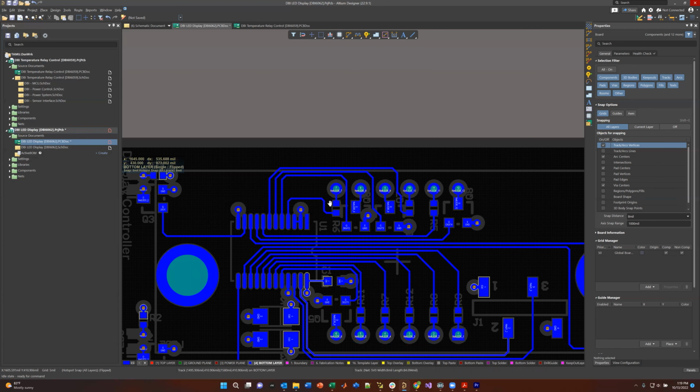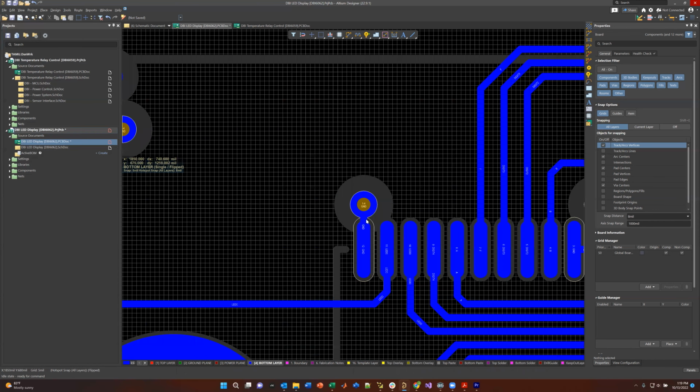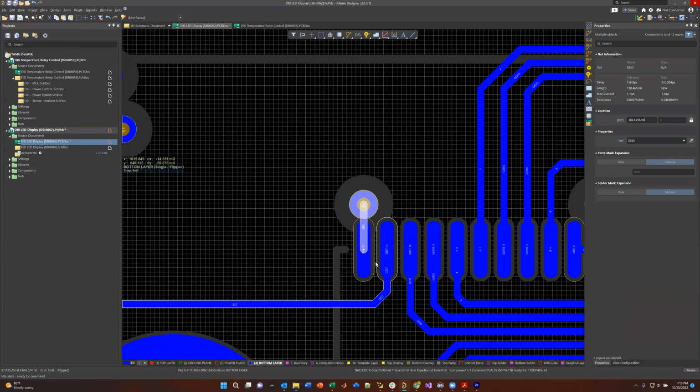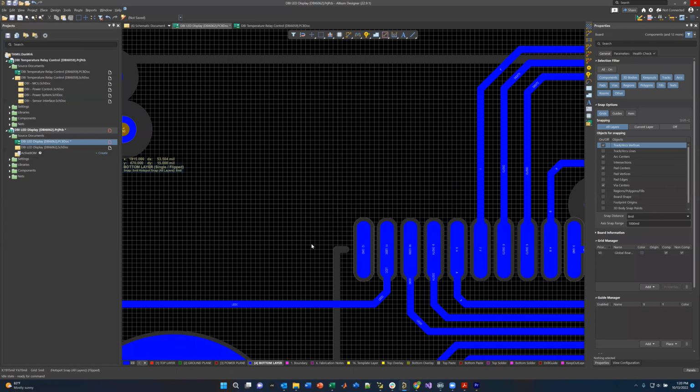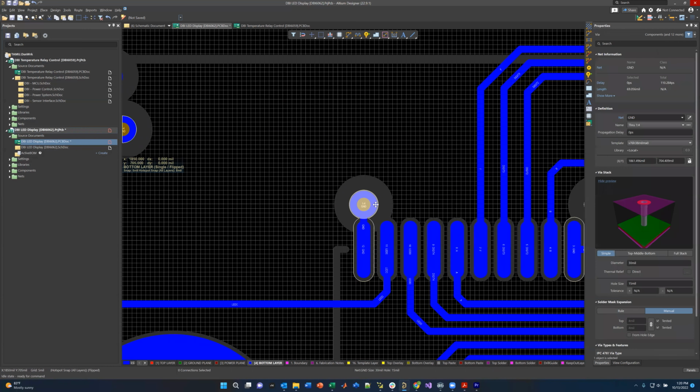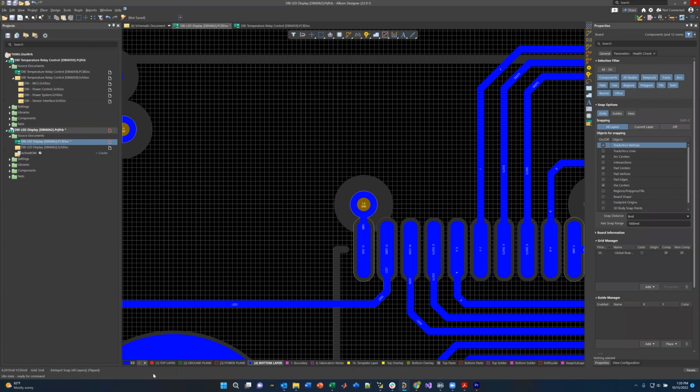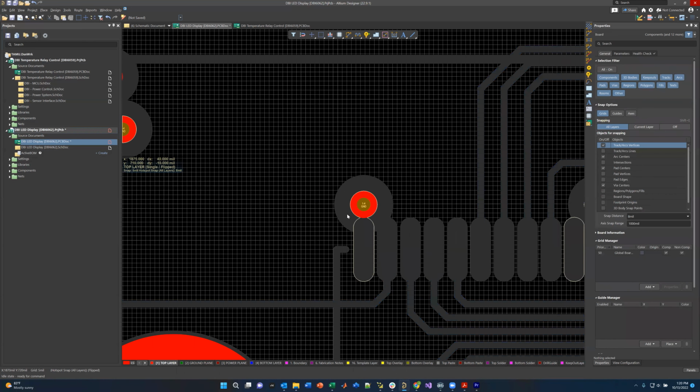So let me show you the advantage of a 4-layer board. We have ground here. This pin here is connected to ground, and so we have this trace and this via. This pin needs to go to ground. This is known as a via. This is a barrel through the board. It's drilled all the way through, and has what's known as an annular ring. That's the blue part here. Of course, on the top side, it's going to be red.